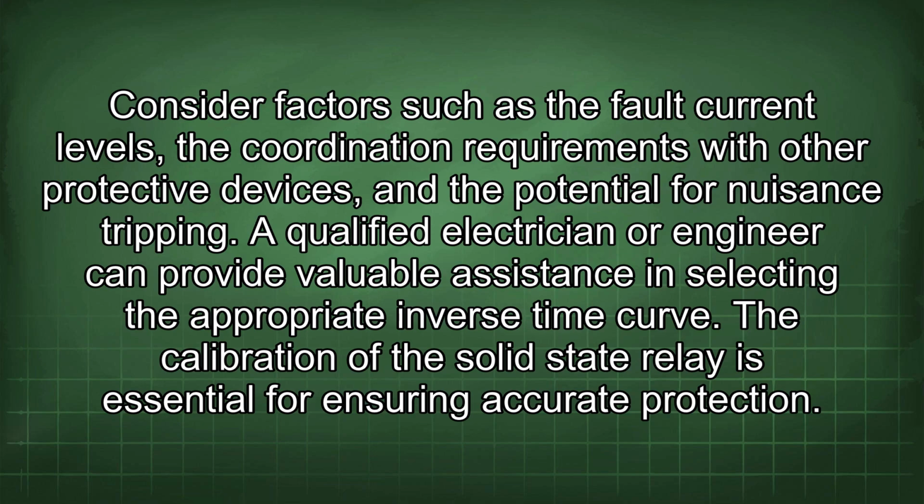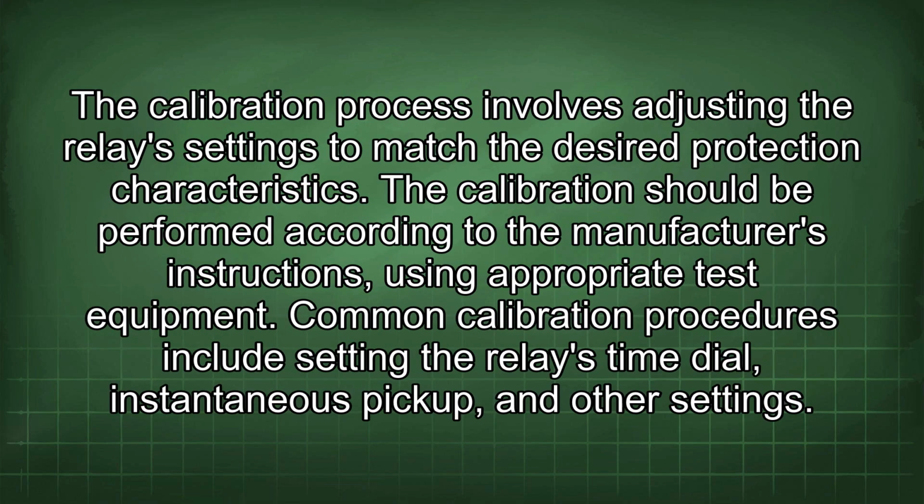The calibration of the solid-state relay is essential for ensuring accurate protection. The calibration process involves adjusting the relay's settings to match the desired protection characteristics. The calibration should be performed according to the manufacturer's instructions, using appropriate test equipment.